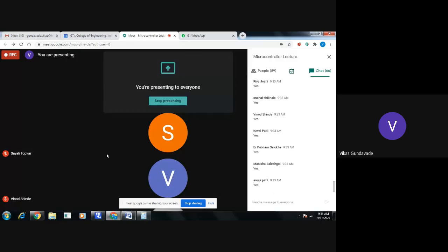At the same time, we can take two switches also, and we can do the same program for transmission of data. During the reception also, the same process will be done. But for the reception, we need to enable the receive enable pin, and whatever data is received will get stored into the memory location. Whatever data is received at the S buffer will get transferred to the particular memory location. So this is all about this serial port programming.